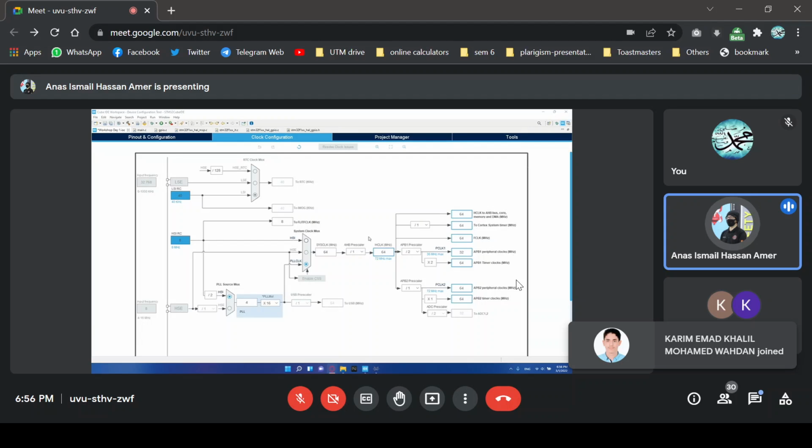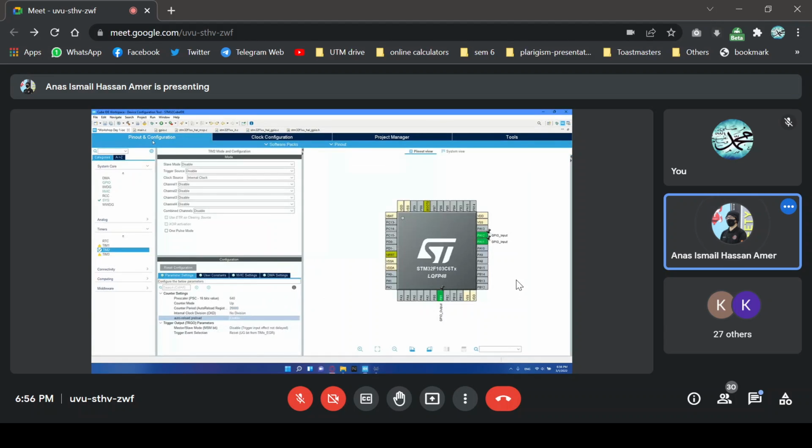By delaying the main program, you stop the execution of all other tasks. But if you use an interrupt, then your main program can continue working while the interrupt happens. We'll see that when we get to the code part. The interrupt will be totally separate from the main code and will run separately.